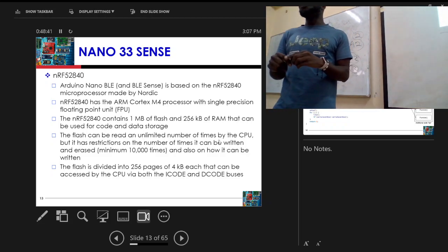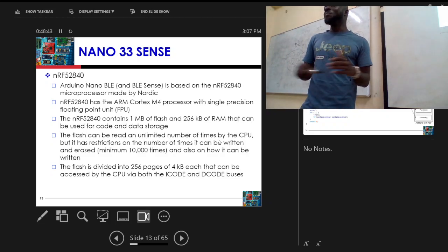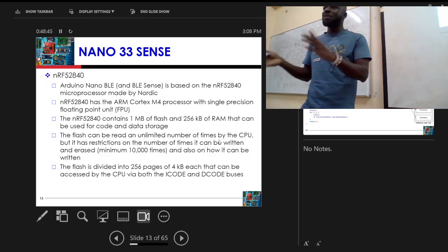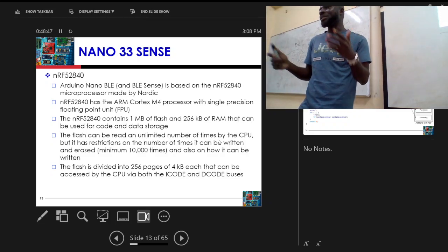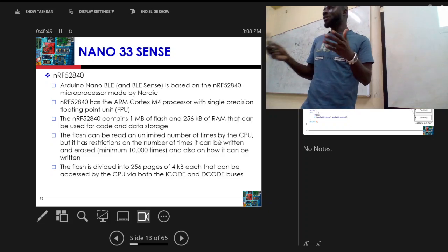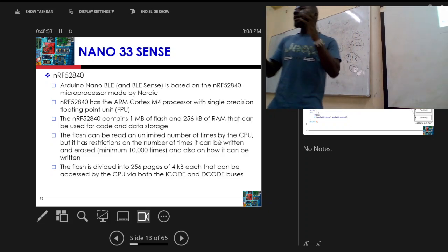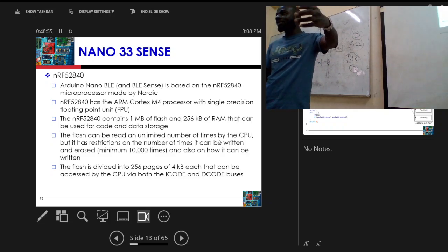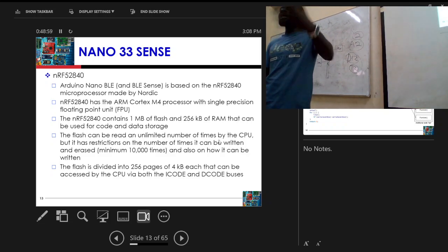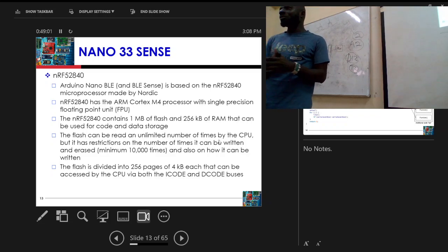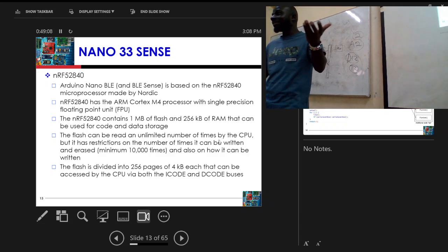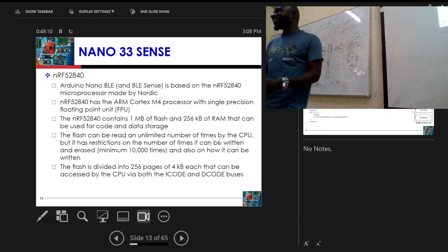Some of you will be making very simple errors and then programming the Arduino. It's not advisable, right? Why? Because the flash weakens anytime you program the Arduino board. You guys know that, right? It's memory. Memory degrades anytime you load something onto it. Anytime you write a memory location, it degrades. You guys know that, right? As engineers, you don't know that.